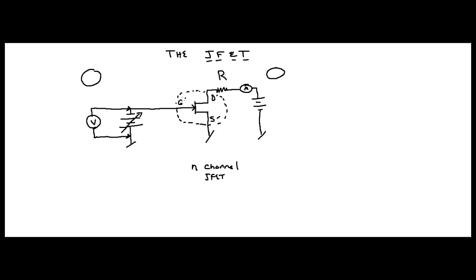And your gate, that's the voltage at the gate, right? That's what you're going to use to control it with. Here we have a battery, and we have this arrow. That means it's variable. So you have a variable power supply here. And this is minus on the top and plus on the bottom. So the greater that voltage, the more negative your gate becomes. All right? Because you've tied your positive portion of the battery to ground, right?